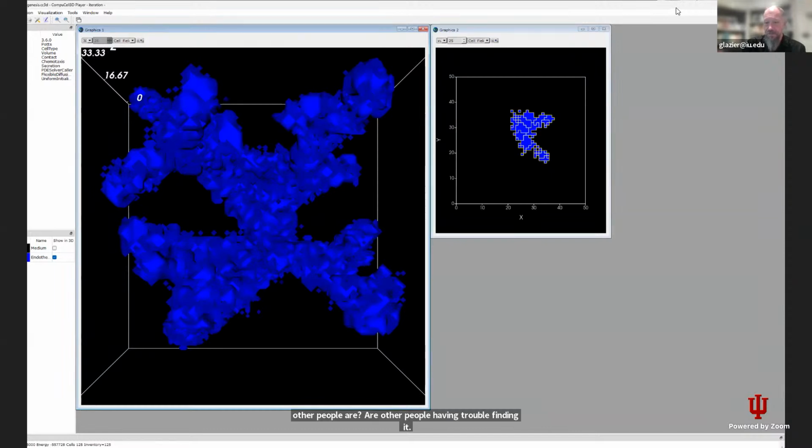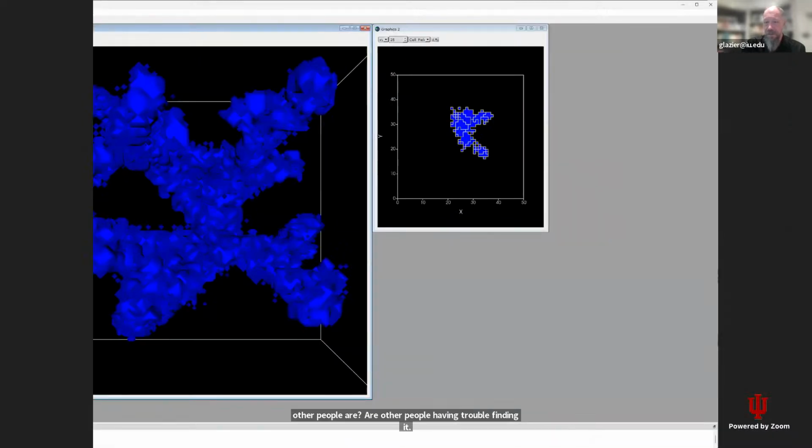It's there, but it is having an issue on my screen because of the Zoom share with pulling it down. Pull down XY, select 3D. To get that pull-down to appear, you have to have done at least a single step. So if you just launch it, you have to hit one step or hit run before it will work. And now hit play again.